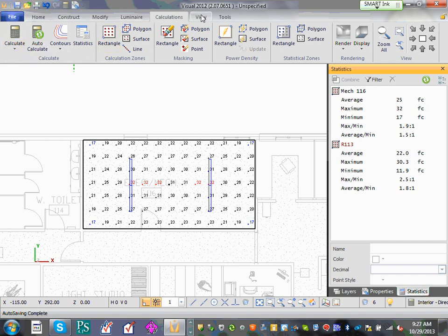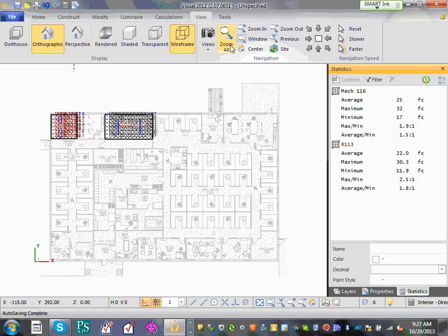Any question about doing all these steps for every single room? So what I expect from you guys this week and next week is basically take every area, build exactly what we have done, run the calculation. You might have to adjust it like Andrew had done. And then when you're done, we're going to export to CAD, import to Revit, and do our layout and tagging and switching with Revit. That's the most important thing. That's the Revit part.